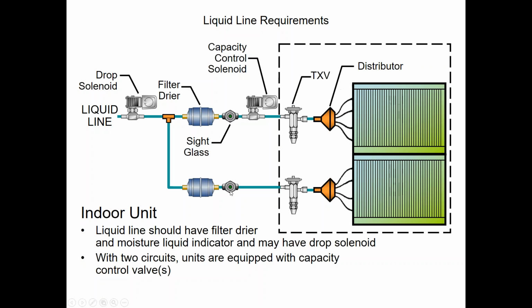Now, the sight glasses here, when we put them in, that's great. That will tell us if we've got a solid column of liquid at the TXV, which we always want. We don't want flash gas through here, which you still could have on minimum loads once in a while. But sight glass charging is not for the new equipment. All the new equipment, really, you're best off charging by weight. At least for the absolute minimal charge, which I've got some slides coming up on we'll look at.